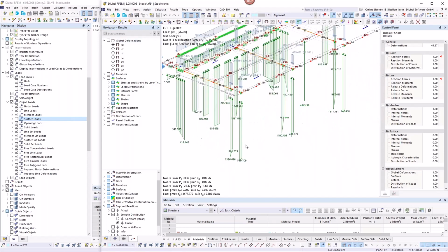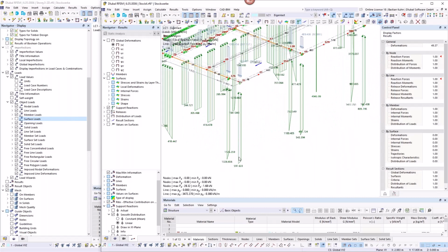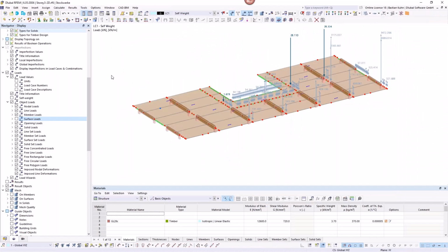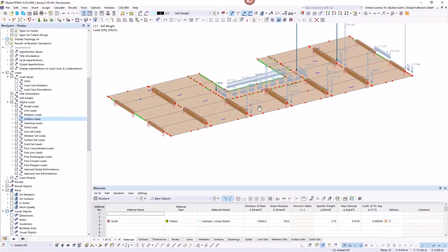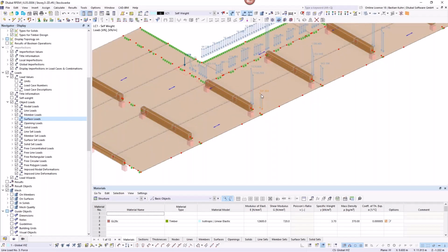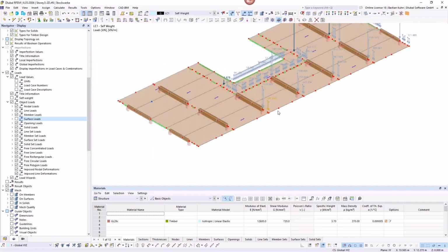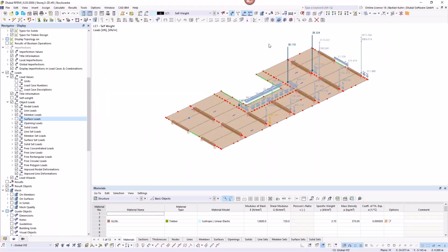So that really is the load transferred from this model into the other. And maybe we also take a look at the line load here. So 591 here, and then I think it should be enough. And right here, whoops, you see also 591. So yeah, that fits. The load is correctly transferred from, I would like to say, story 13 to this part that we are analyzing here.